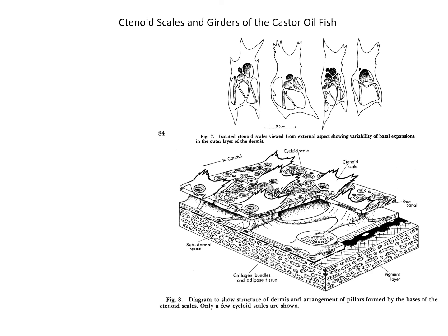And so on one side, when it's expanding, it's thought that fluid is pulled in, and that's going to be fluid from the boundary layer, right? So that's going to act, as we saw in the movie, when you suck the boundary layer in, it's going to help to keep the rest of it attached. And then when the flow is ejected, it's going to impart momentum to the boundary layer.